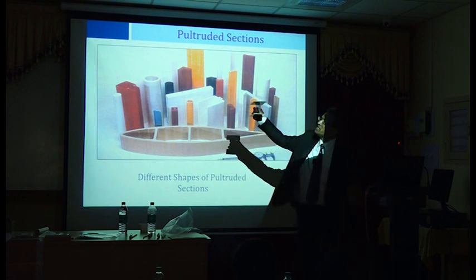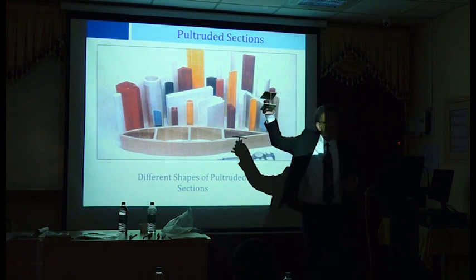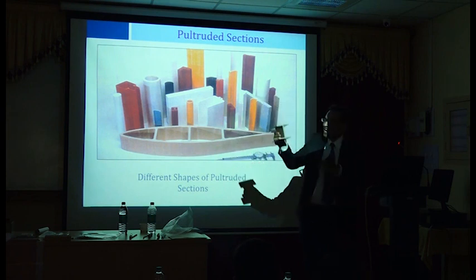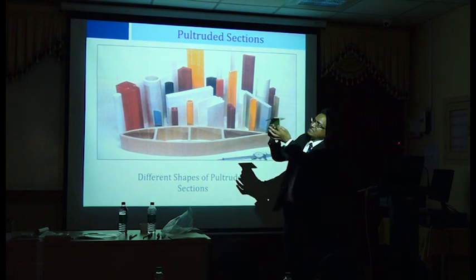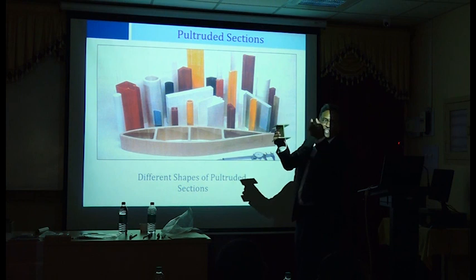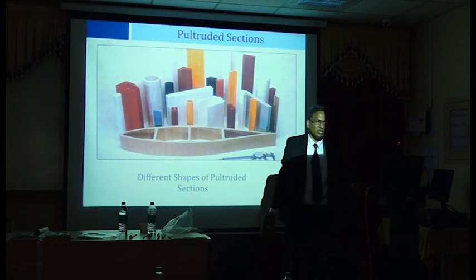But if you see this section, the thickness here is the same as this thickness here and this thickness here. There's a reason for that, because they are very weak in buckling. So they have made this stockier, thicker, made the web thicker. So you will see if you apply the steel code to design of this, it will not work.